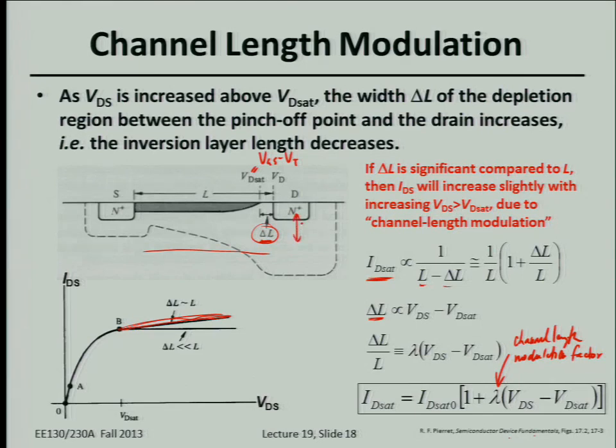That's true. In the MOSFET design project, you'll find for various reasons that to suppress leakage, you might want to dope this channel or body region kind of heavily. But then, in the off state, you're going to have high VDS, so you have a large drain voltage in the off state and a reverse-biased P plus N plus junction, and you'll have breakdown. You're right, so you get tunneling. You'll see when you simulate transistor behavior that if you dope the channel too heavily, the off-state leakage starts to increase, and it's because of tunneling at this PN junction. So that is a practical concern for modern CMOS devices.